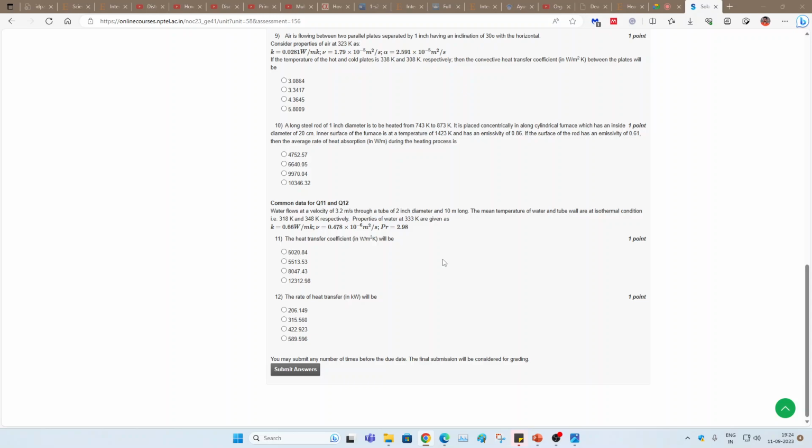From there, you know the Reynolds number, you know the Prandtl number, so you will get the Nusselt number. And Nusselt number equals hD upon k. You know the diameter, you know the k value, the thermal conductivity, and what is needed is the heat transfer coefficient, so you can get the heat transfer coefficient h. Rajeshwari, can you get the heat transfer coefficient value? If you could not understand, I will repeat it again. The portion you don't understand, please ask me.